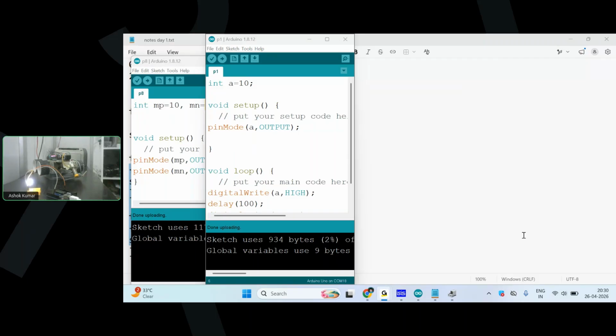depending upon the reliability and the capability of your controller. Because what is this process actually doing? Consuming the current, turning it off, which means producing an abnormal process which causes the heating of your IC. So if it reaches a temperature which is not good for the IC, it may burn. That's the reason why we do not connect the IC directly with a 5 volt motor. Because it's not only about voltage, it's about current also. So the voltage was absolutely fine, but current ratings also we need to check, right?